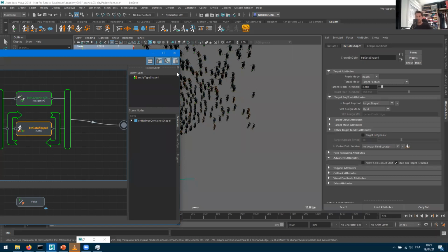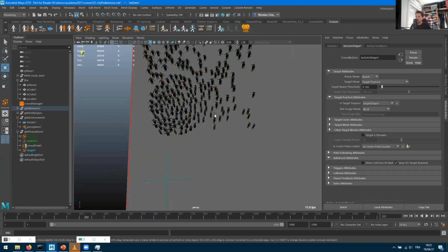The target is dynamic checkbox. Yeah, that's correct. Fetching information from Maya takes a lot of resources. In Golaem, we're fully multi-threaded on entities, but every time we need to access some data from Maya, it's not multi-threaded everywhere. So we're sometimes losing performance every time we need to ask Maya something.